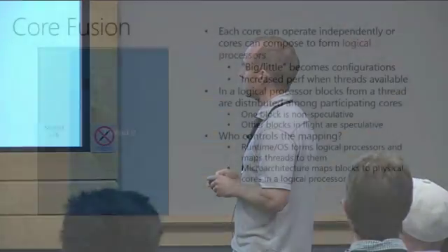Okay, so I can be running some number of cores just doing continuous sensor processing and analysis to ask, is there something I should be paying attention to? Those are typically loops. So I can just be sitting there issuing instructions, and I can dial down the clock rate just to be able to ingest that input data fast enough. And then when something interesting happens, I can spin up, fuse all the cores, and run at it very hard. This is a very high performance but also energy efficient substrate. This would be a 16 wide issue sort of mega core.